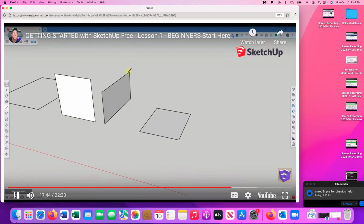And so let's say, for example, that I have this rectangle right here, and I want this to become, not a cube, but more of a 3D rectangle. So you can see how I'm coming in here and drawing out all of these different edges. And by the way, to lock to an inference, you can hold the shift key in order to lock that along whatever your inference is. So as I hold the shift key down with this tool active, whatever axis inference I have active, you can see how that's locking in. So now I can draw a line that lines up with one of these edges just by holding that shift key.